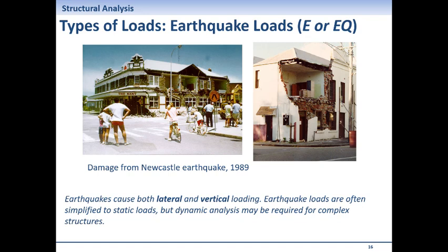One is called equivalent static loading, which is, compared to the others, an easy way of approximating earthquake loading. So in that way, earthquake becomes static, but it's not, it's dynamic. But we have developed trustworthy equivalent static loads to estimate actual dynamic earthquake loads to be able to design the building for ordinary buildings.